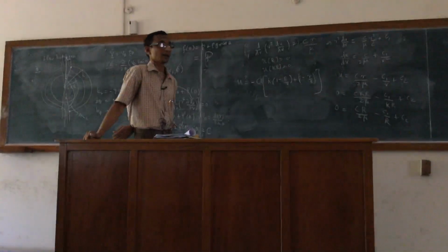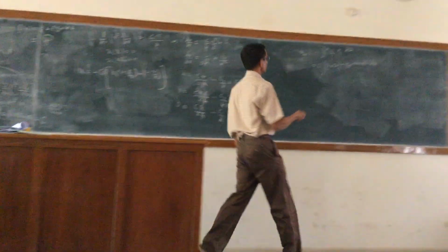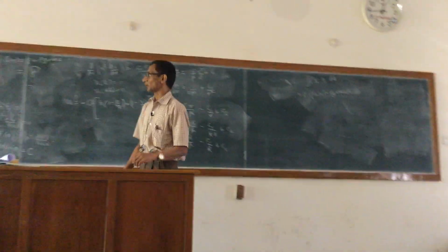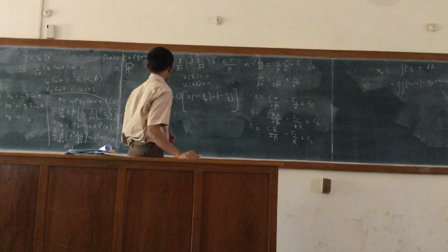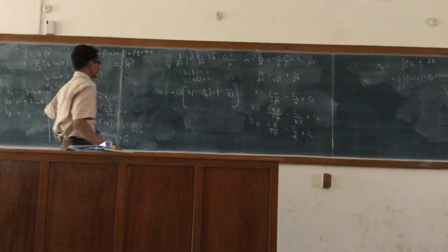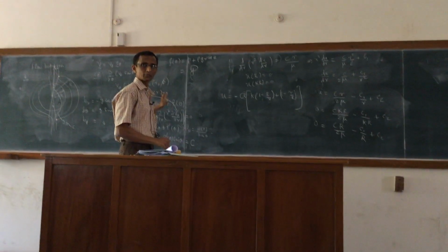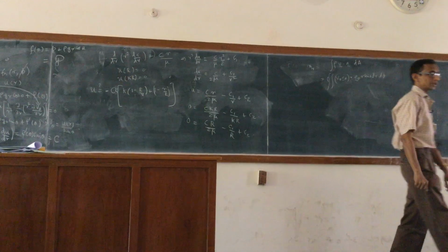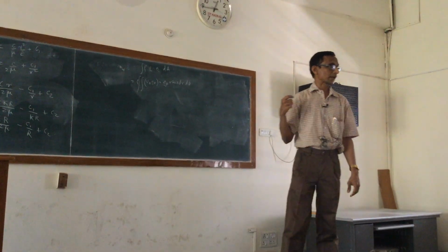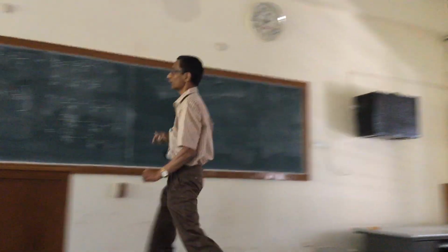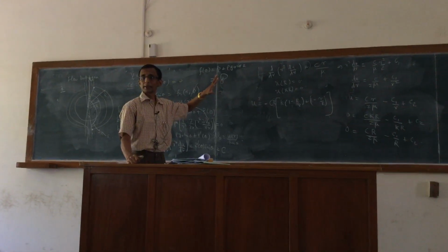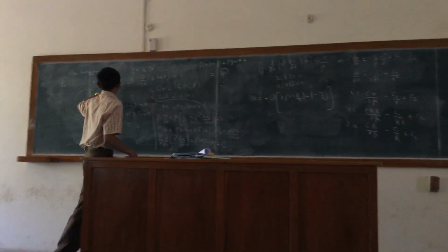Now, what are the limits of integration? Since this is v_theta, the sin theta will actually get cancelled out. You have to think about what is happening here, because after all, this integral seems to be dependent on sin theta. So in principle, it depends on where you calculate the flow rate. However, the fact that v_theta is inversely proportional to sin theta will make the whole integral independent of sin theta, so it doesn't matter at what particular angle.